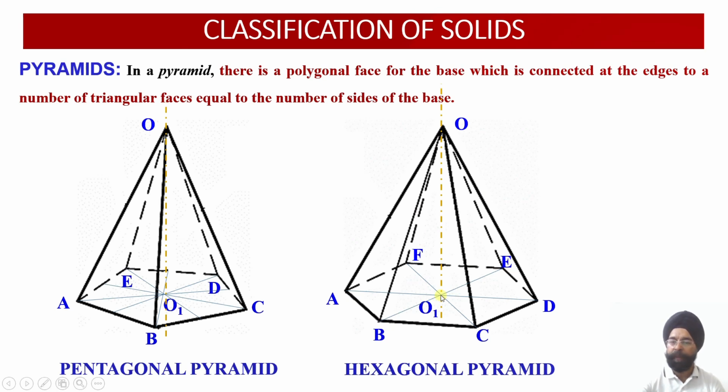In case of an oblique pyramid, 6 projections you are required to draw, 3 on the elevation side and 3 on the plan side. So 6 into 8, only 48 points will be required compared to 84 points required in the case of the hexagonal prism. So pyramids are easier to handle as compared to prisms. But otherwise the principles remain the same.